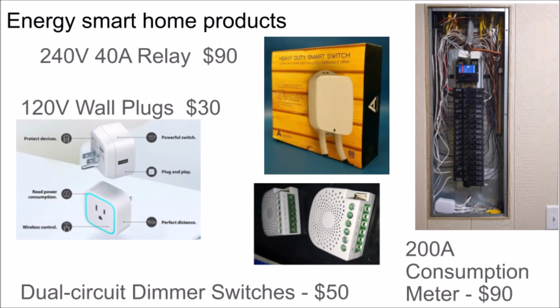But by building a site energy controller, either with expensive top shelf commercial product or more modest open source hardware, the same result is that the system can save the building money on their electric bill while being grid tied, and then also allow for more flexibility of on-site backup power for the whole building during an emergency while that building is being powered with an undersized generator, such as a gas generator or a solar battery.